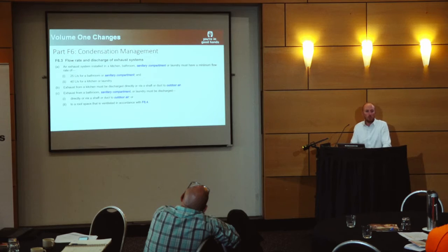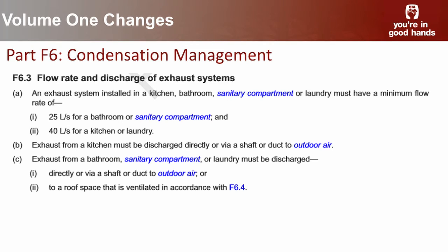Yep, it can be that. It depends how you do it. There's a few different options, but some might be a riser shaft throughout the whole dwelling, or it could be slab to ceiling. No, it just needs to be ducted to the outside. When you're in the roof space, there are ventilation requirements for that roof space, but that's really for the other ones, because for kitchen exhausts, it is going to need to duct to the outside.